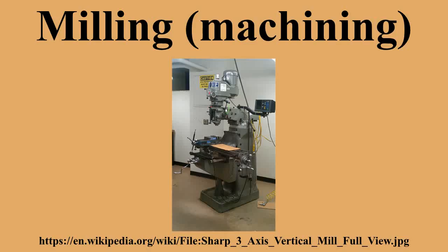Jig bore: vertical mills that are built to bore holes, and very light slot-to-face milling. They are typically bed mills with a long spindle throw. The beds are more accurate, and the hand wheels are graduated down to 0.0001 for precise hole placement.